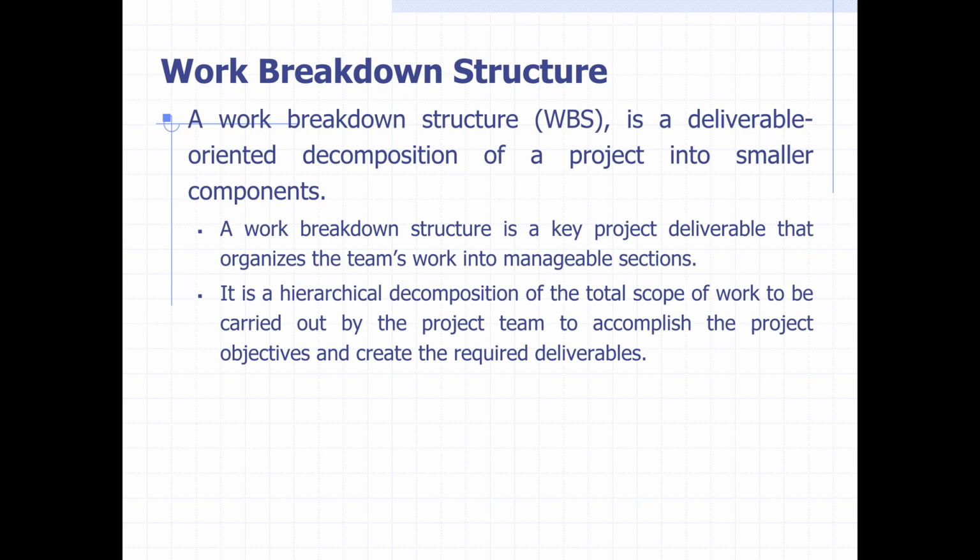Okay. So in the next slide, we will put an example for a home construction project, how we are going to divide it into WBS. Say for example, if a building, we can divide it into the foundation work or structural frame, and then we can divide again: there is piling work or excavation or pile cap. We can separate the pile cap up to the lower level, fixing of reinforcement, fixing of formwork, casting of concrete, and even the steel reinforcement, we can separate that in more detail, like preparing the shop drawing, or cut and fabricate those rebars. So first we have to make the WBS, and then under the WBS we will assign the activities and the durations.